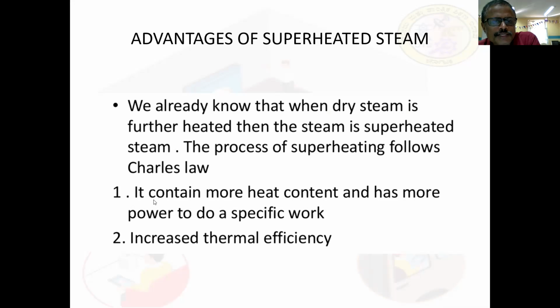So what are the advantages of superheated steam? Superheated steam has more heat content and it has more power to do work. It does more work when it is passed through the turbine blades. If you pass wet steam, or only dry steam, through the turbine blades, then less work will be done.